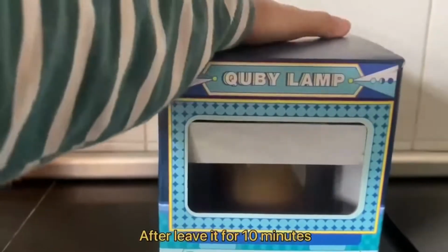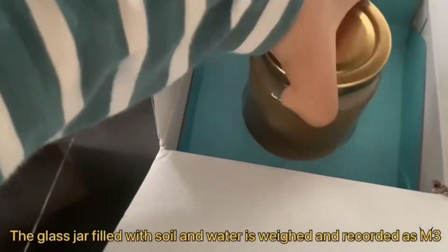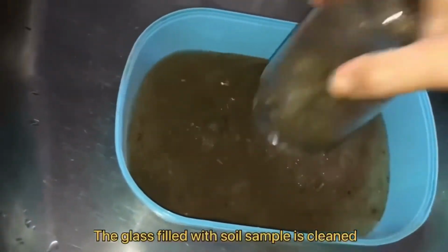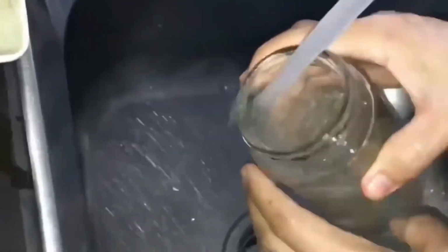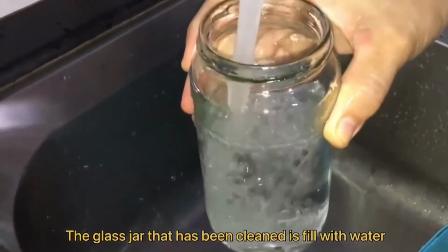After leaving it for 10 minutes, take the glass jar out of the vacuum. The glass jar filled with soil and water is weighed and recorded as M3. The glass jar filled with soil sample is cleaned until there is no residue left in the jar. The glass jar that has been cleaned is filled with water.